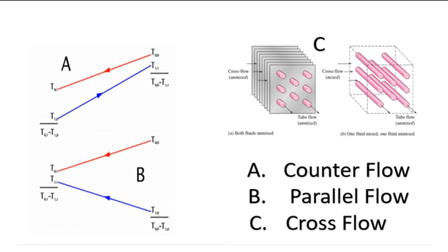Fluids flow in opposite directions and are used for liquid-liquid, condensing and gas cooling applications. Units are usually mounted vertically when condensing vapor and mounted horizontally when handling high concentration of solids. In parallel flow heat exchangers, the two fluids enter the exchanger at the same end and travel in parallel to one another to the other side, thereby minimizing the temperature differences.